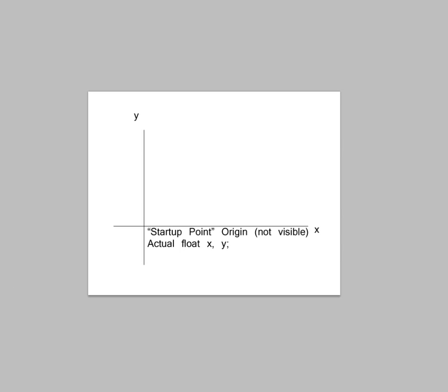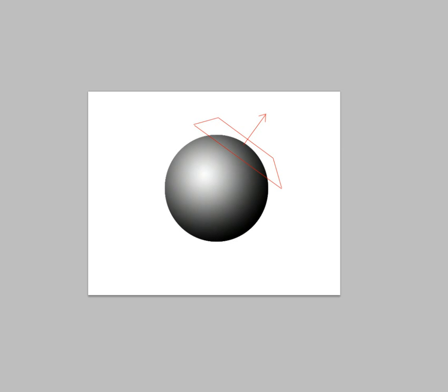Second, you need to keep your drawing within 1 mile of the startup point. There are 2 reasons for this. The first is that the Revit page you look at on the screen is like a 2-dimensional page pinned to the surface of the Earth. If you go too far away from the origin, altitudes and positions don't really reflect their actual earthbound positions anymore.